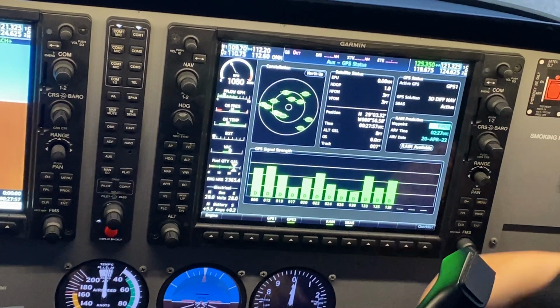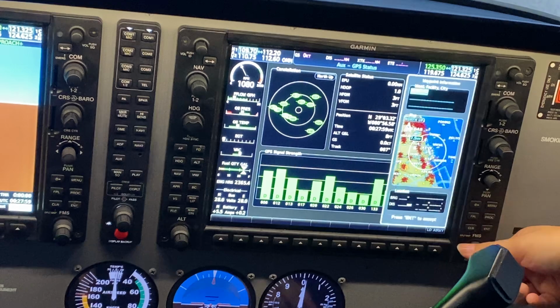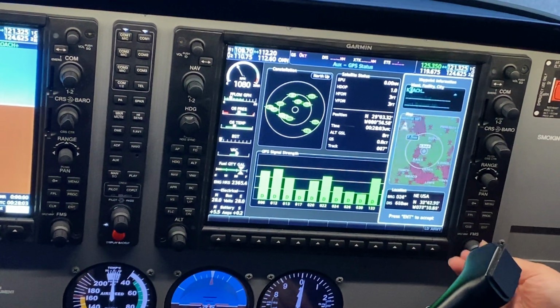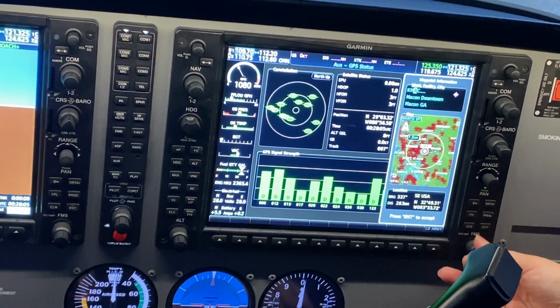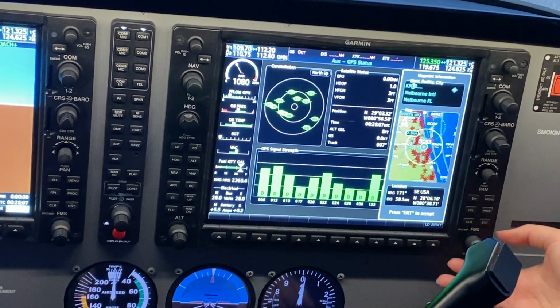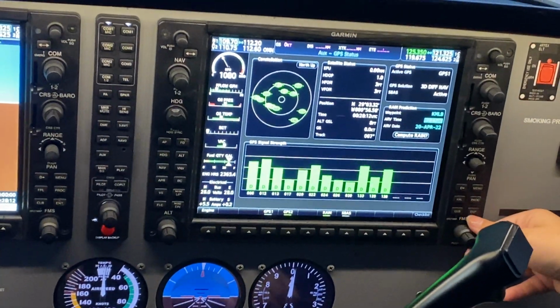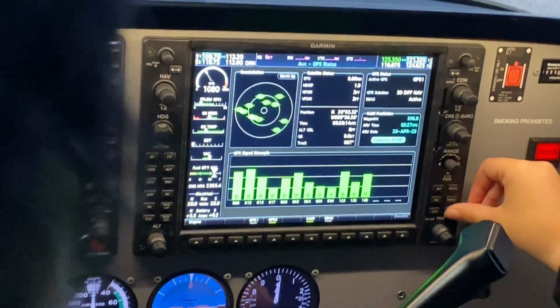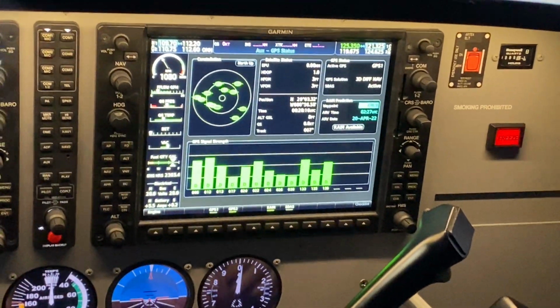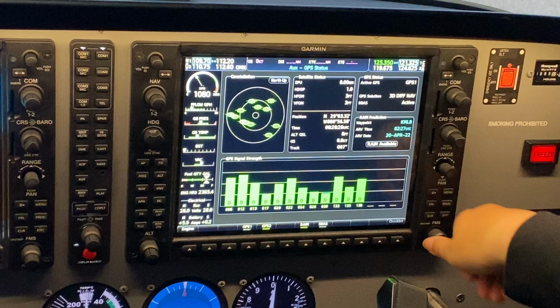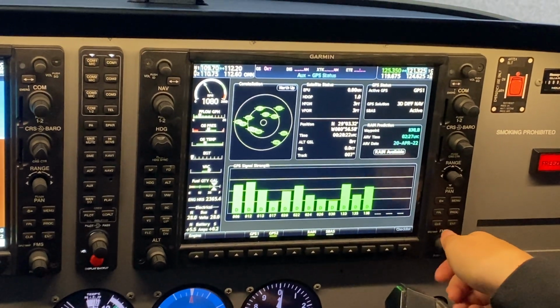So, if we were going on a cross country, we might put our destination by scrolling with the small knob K, big knob M, small knob L, enter, and then checking our arrival time, our date, enter, and computing whether RAIM will be available at that position for that time. Still, we have WAAS, we don't need to do that, but we're still gonna check that.